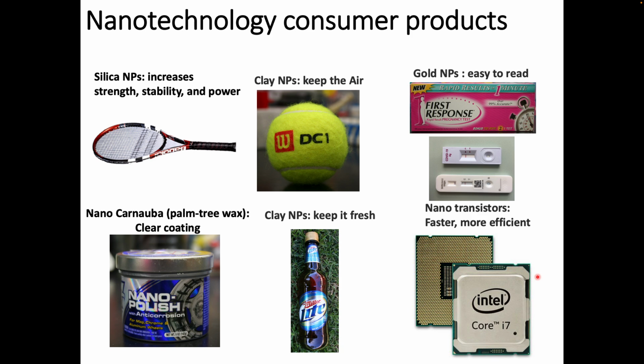Okay. Now another issue is that because we are adding so many transistors in the chip, the critical bottleneck is actually heat. Because there are so many working machines in the given size, and it's all producing heat, right? As we supply the current, and as long as there is a resistance, we have Joule heating, right? Joule heating is I squared R. That creates so much heat in a given space. So how effectively can we dissipate the heat? That is actually the critical bottleneck.